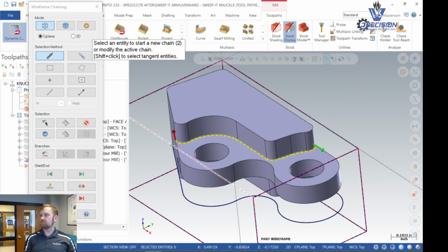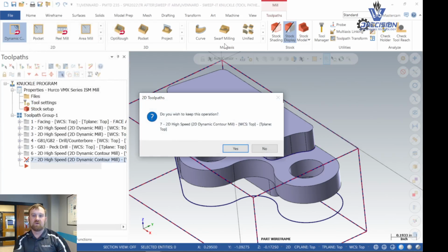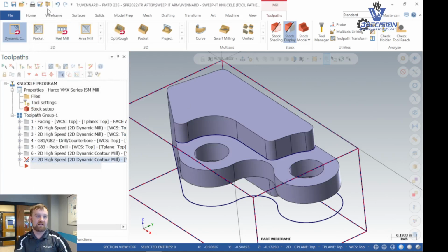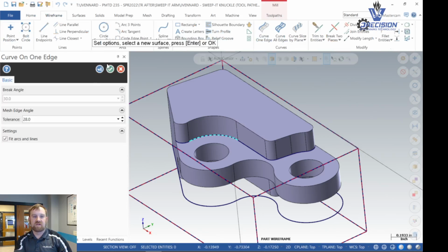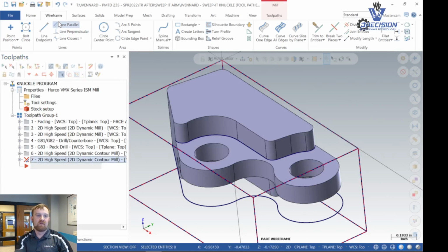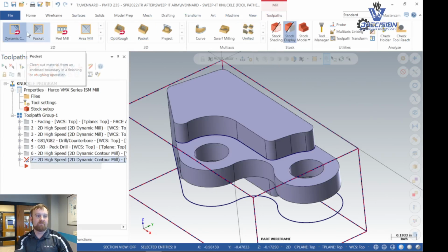Now, yesterday I had a couple people that clicked one edge twice, so it created the curve on the edge twice. So they had an overlap, and they had to go back and delete duplicates. So you got to be careful of that. I'm going to do it real quick just so you get to see it, since nobody's done it in here. If you accidentally click one extra time here, you get 2 arcs there, and then I go to create the toolpath,